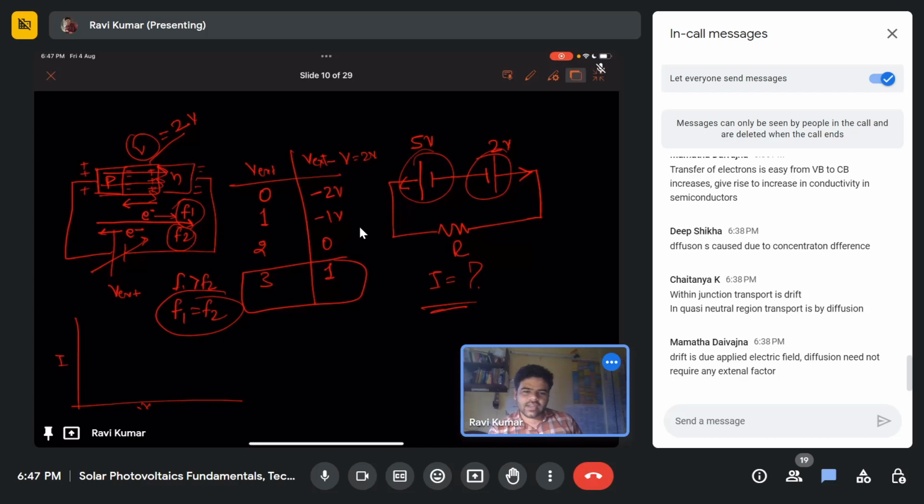No, you are not getting it right. Sir, I got till this point, sir. Initially, when the applied external voltage is less, the junction voltage itself is more. So the current flowing through the circuit will be because of the PN junction potential, so that will be very less. But as soon as you increase the external voltage, the current will increase slightly only up to the knee voltage point. Afterwards, the external voltage will completely dominate, and then the current will rise steeply.